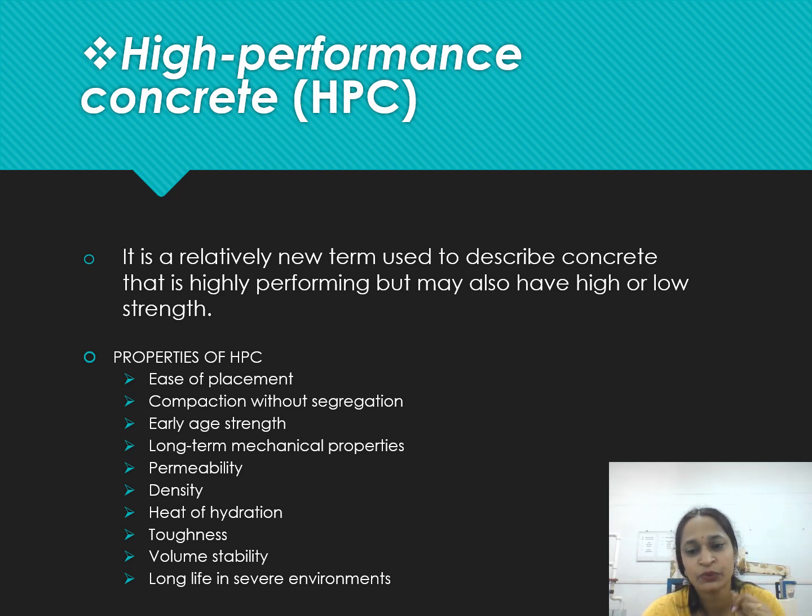Water percolates through those micro cracks, and then it gets into the reinforcement, and then you know the story, it starts to corrode, and the structure as a whole comes down. So this is important that we maintain the mechanical properties.